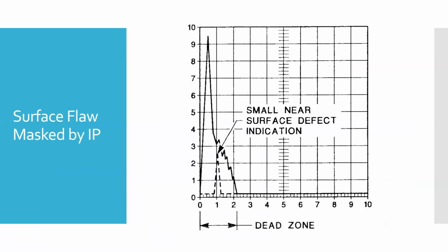So we're going to do this manually when we do it. To attach our probe to the surface, we're going to use a glycerin or glycerol-based gel. It's a clear gel. But there are other ways we can do it too.